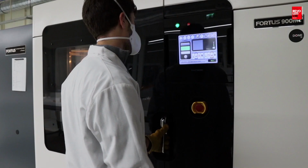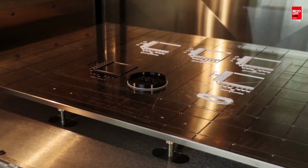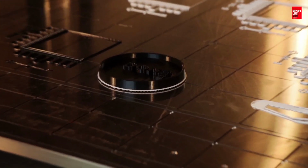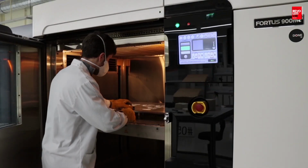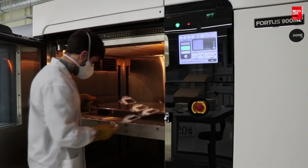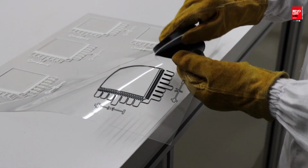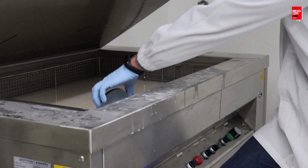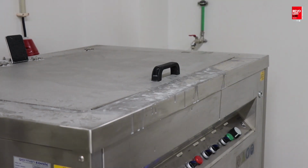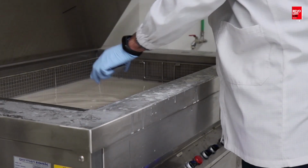After we make the production, we can remove the part from inside the machine, and we should take care about removing the parts from the foil. After we remove the foil, we can put the part inside a tank with a specific liquid in order to remove all the support material.